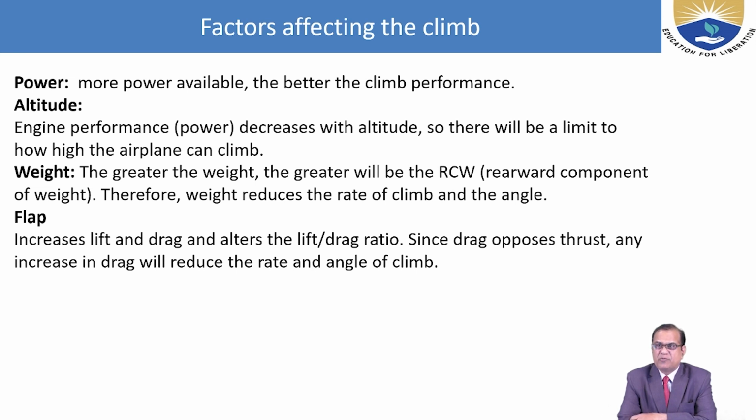Drag opposes the thrust, so we need more thrust, and an increase in drag will reduce the rate of climb and the angle of climb.